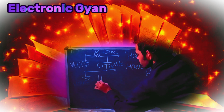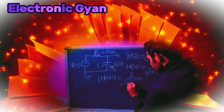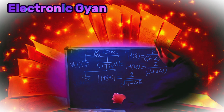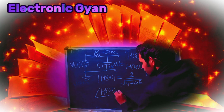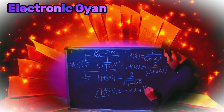Here the magnitude response, the magnitude of H(omega), is equal to 2 divided by square root of 4 plus omega squared, and my phase response, the angle of H(omega), will be equal to minus tan inverse of omega by 2.